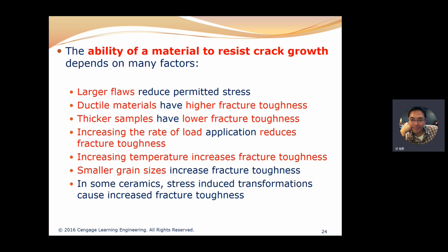What does that mean? Think of a tensile test on a metal that already has a crack inside. If we pull it quickly, or pull it very slowly, which rate will reduce the fracture toughness? Of course, the faster rate of loading, or pulling, in the tensile test.